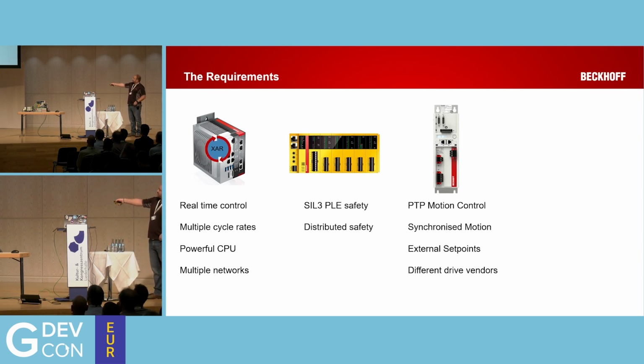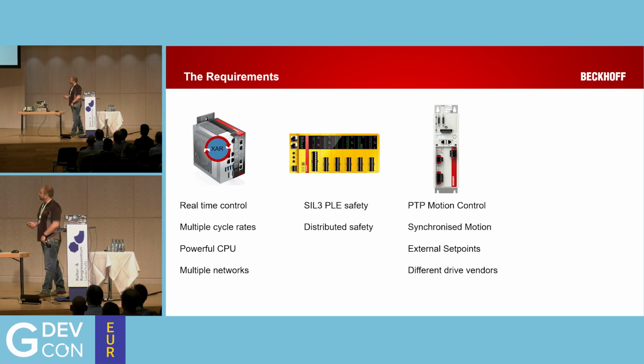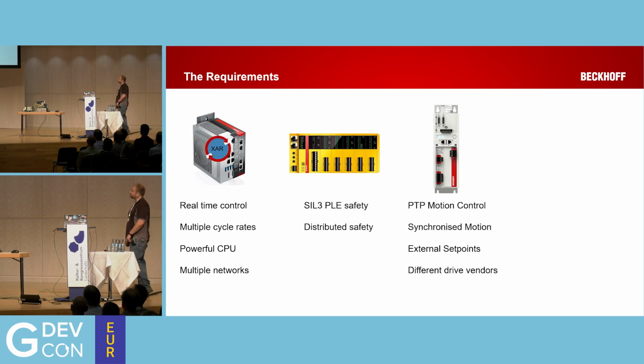And we needed to actually run external set points. For some of the experiments, the customer had a set of known positions they wanted the system to go through, and didn't want to bother programming it with standard motion control systems. They just wanted to feed external set points directly to the drives. So we needed to be able to achieve that as well. And due to sizing, we had to incorporate not just Beckhoff drives, but different drive vendors as well. So we needed an open platform that would let us do that.